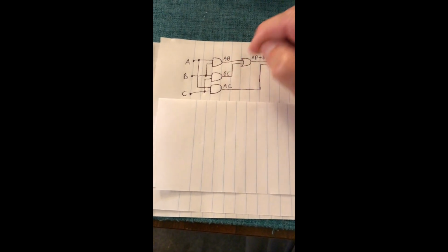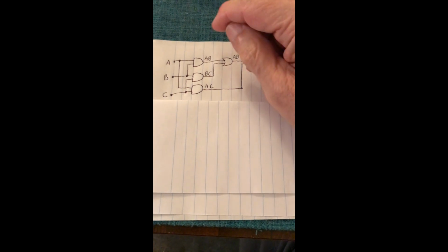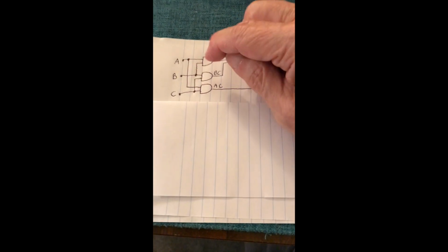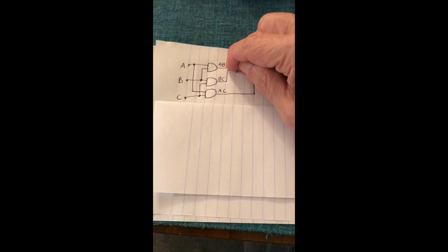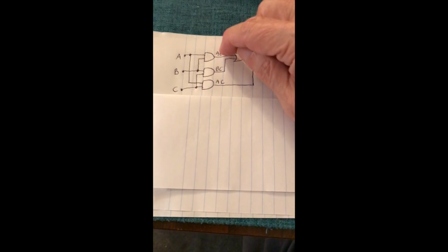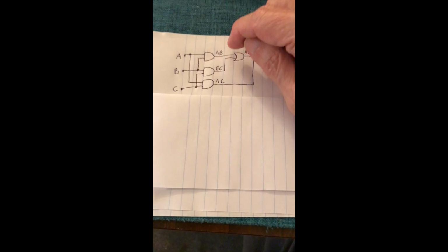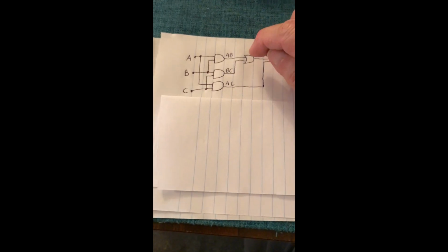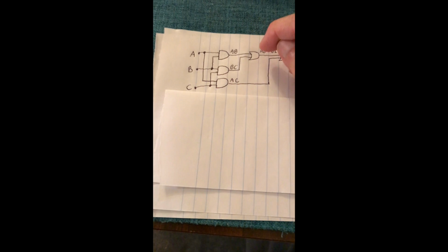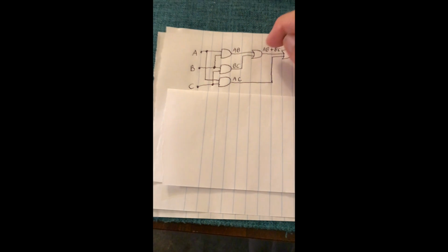And we've got a little bit of Boolean logic symbolism going on here. Signal A is ANDed together with signal B in this gate and produces the output represented as AB, which is like A times B in arithmetic. It's going to behave like A times B in a way that we'll see in a second. The OR gate is ORing together the AB and BC outputs, and the plus sign is used for the output of an OR gate. It's AB, A and B, or B and C, represented symbolically here.